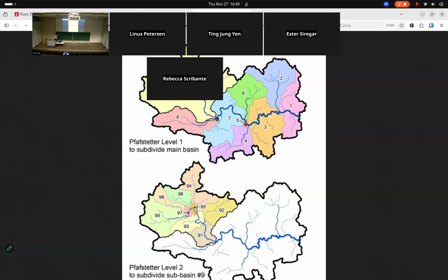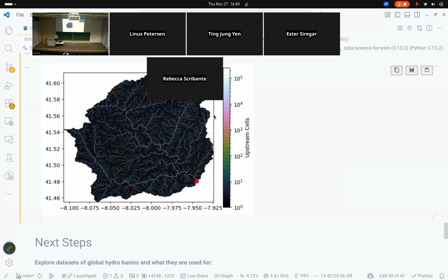So you can layer the catchment areas onto each other, where the dispatch of the upstream run-of-river plant determines the water availability in the downstream river plants. So it's never just about one catchment area, it's a layered system. You would do that for every run-of-river plant, and of course you can have more run-of-river plants in one river, and yeah, that's all I wanted to say.